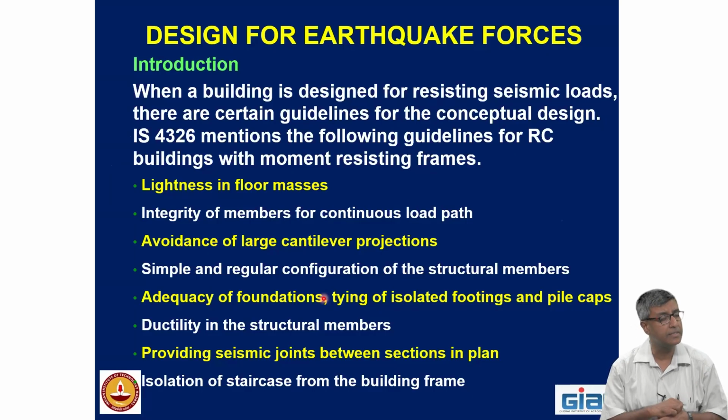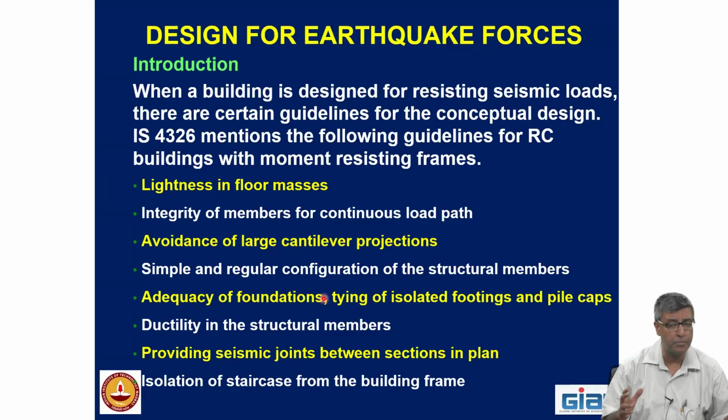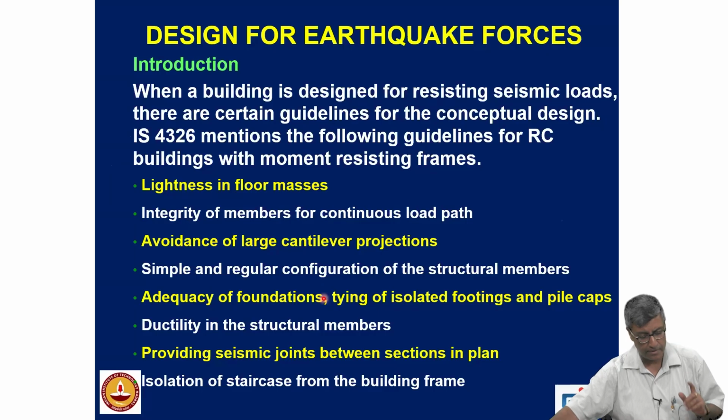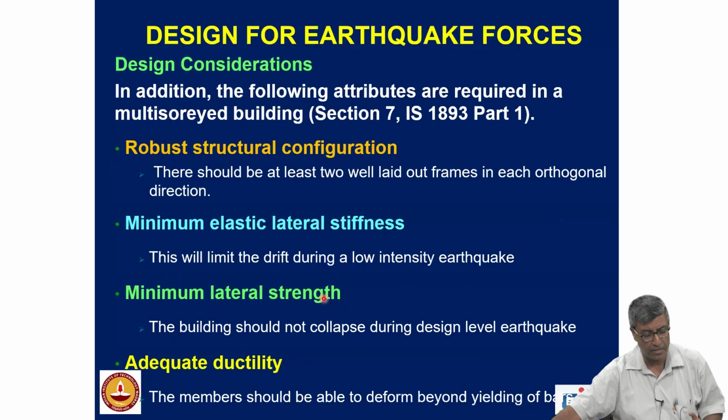Ductility in the members depends upon not only the reinforcement but also on the connections. And if the building has certain projections in plan, we can isolate them. Okay. The staircase has to be properly designed so that it doesn't fail during an earthquake.